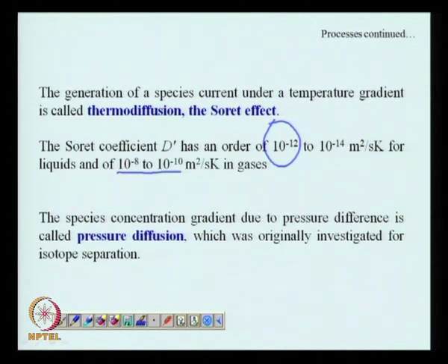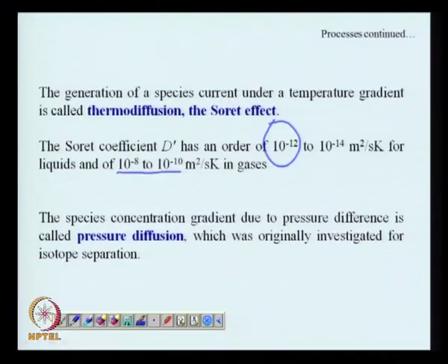But in microsystems, due to the enhanced value of the gradients, the species transport or heat transport by such processes become important. So, this again shows the interdependence of heat and mass transfer in microsystems because of the presence of temperature induced mass transfer and concentration induced heat transfer. The process becomes much more complicated when you go to microscale, and these additional effects which were not present in macro systems become progressively important.